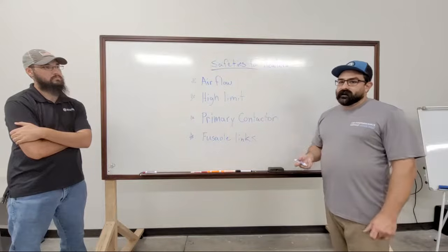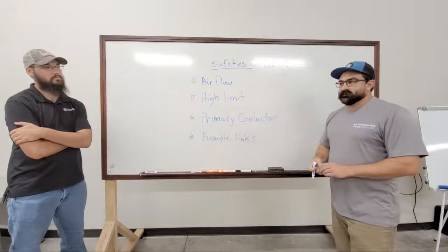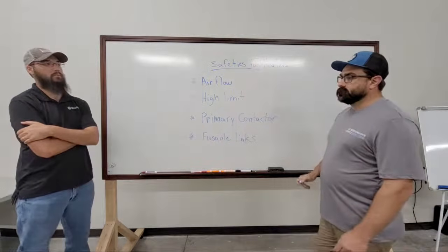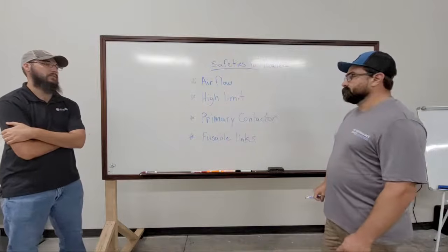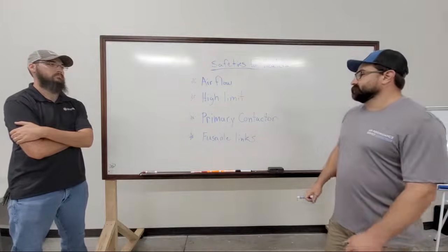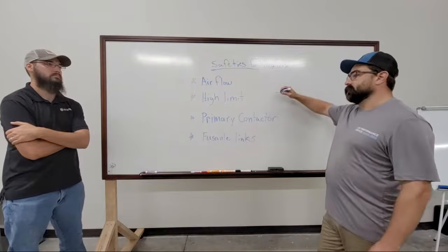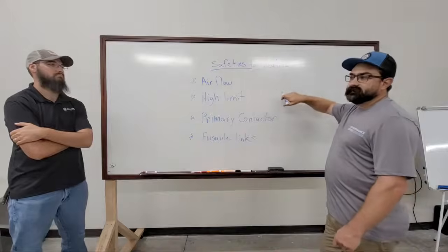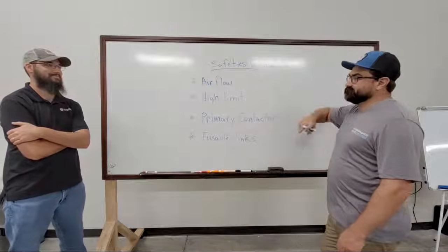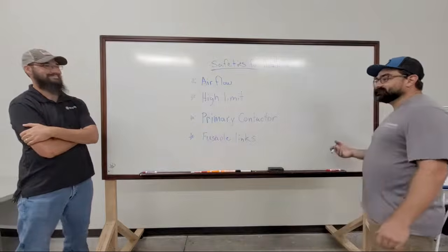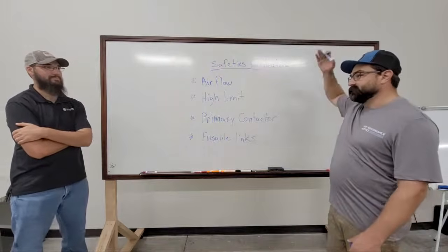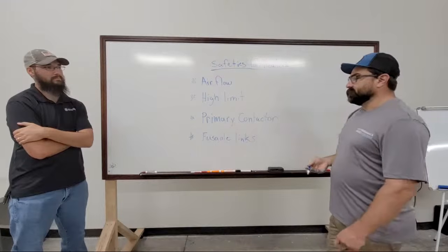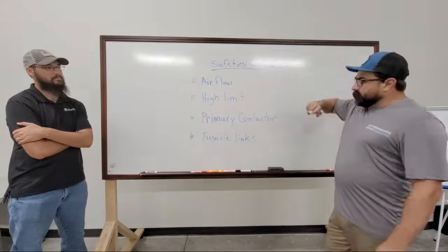It's a way to keep a box from putting out like 140-degree discharge air temperature when you only need 90. And most of them are set anywhere between 180 to about 210. Yeah, it's pretty common. Well, that's the manual resets. A lot of the autos are like at 110, 120, at least in fan power boxes. So, not everywhere, but because like I said, they're being used as a limit for discharge air temperature. But the manuals are set up there so that you don't burn the system down.